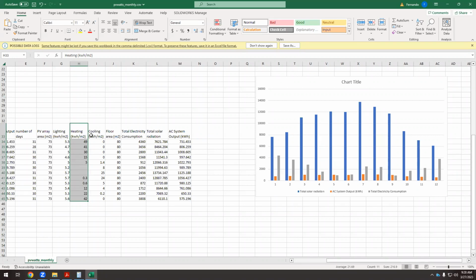So that's the difference between the energy, kilowatt hours, and watts or kilowatts. So probably if we want to meet the passive house requirements in terms of peak consumption, cooling is more demanding than heating. But then we have to multiply the hours that we need the cooling system. So we need more hours of heating system than the cooling system.